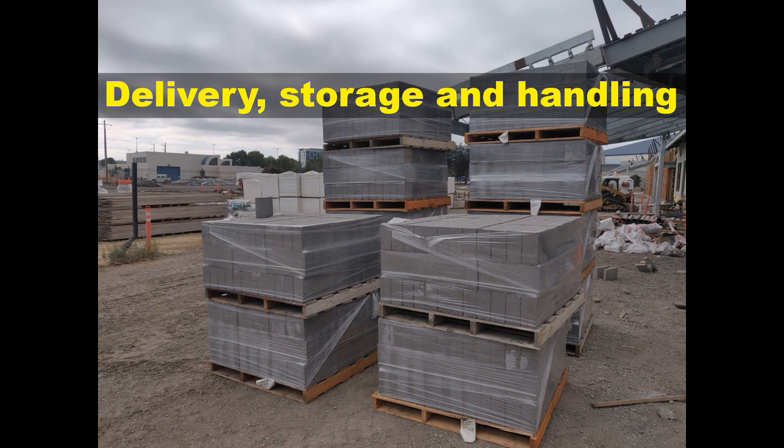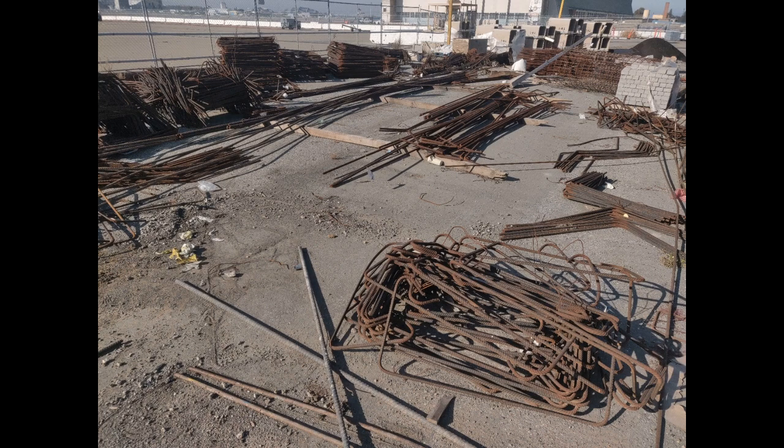Deliver, store, handle, and protect material to avoid chipping, breakage, and contact with soil or contaminating material. Store and prepare materials in already disturbed areas to minimize project site disturbance and size of project site. Store steel reinforcing bars, coated anchors, ties, and joint reinforcement above the ground. Maintain steel reinforcing bars and uncoated ties free of loose mill scale and loose rust.